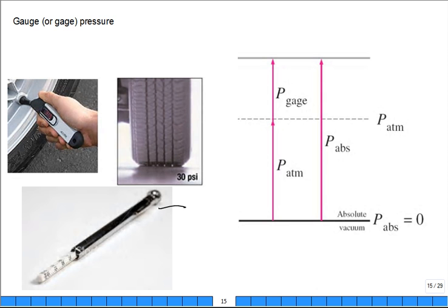Guess what's inside there? S-P-R-I-N-G, a spring. That's what's inside there. And a little rubber plunger. So some air comes out of your tire and fills a tube, compressing that spring. As it compresses the spring with this plunger like this, it pushes out so you can read the indicator.